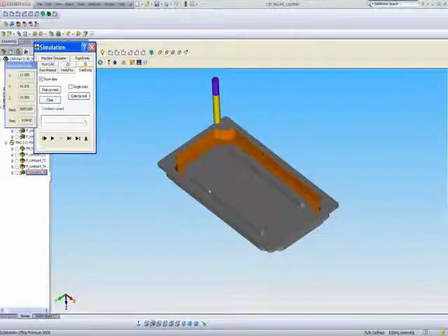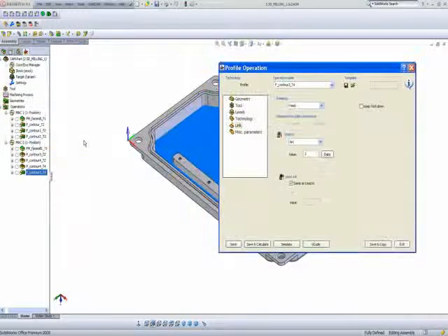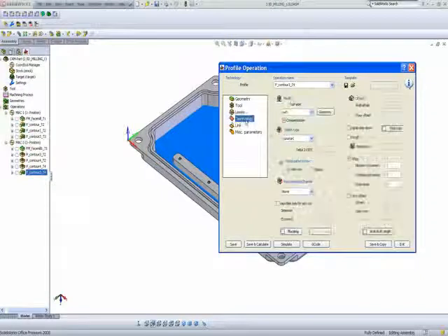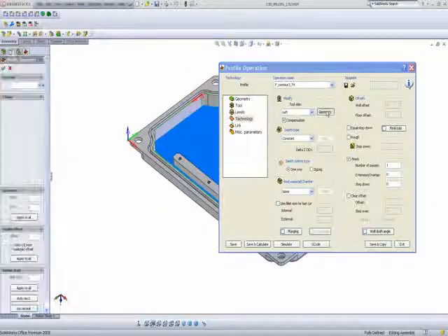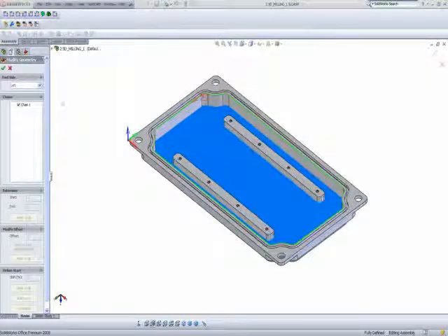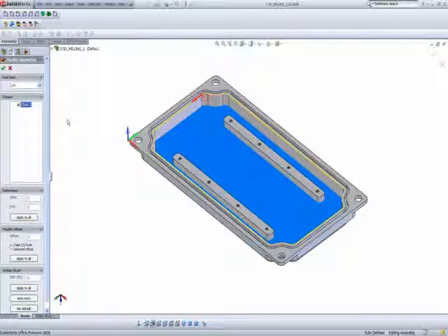Now, sometimes you may say to yourself, you know what, I really don't want to start in this corner over here. I want to start at a different point. I want to start, let's say, at this point over here. This can simply be done by going to my technology area into Modified Geometry. In Modified Geometry, I simply click on the chain and say, OK, define start.